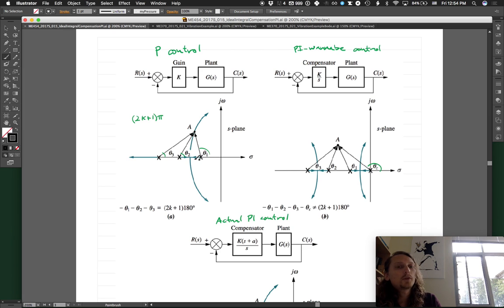And the open loop poles are where all of the root locus branches start, remember that, and then they go towards open loop zeros or zeros at infinity if there are no finite zeros. So we take a look at this situation. This is, say, a third order situation. The open loop poles are all on the real axis, and the root locus would be drawn as shown.